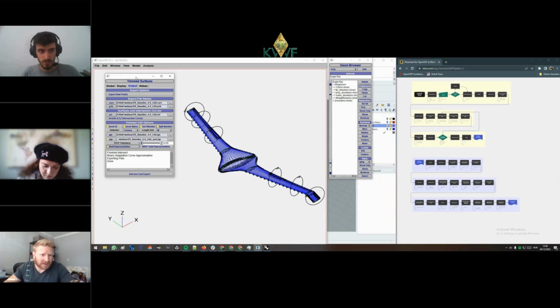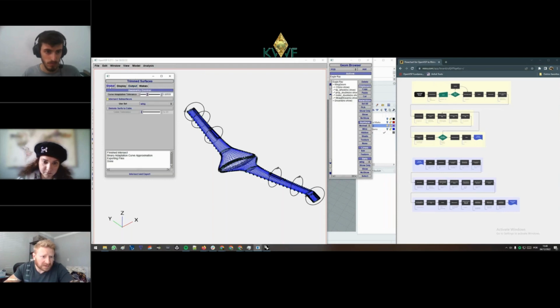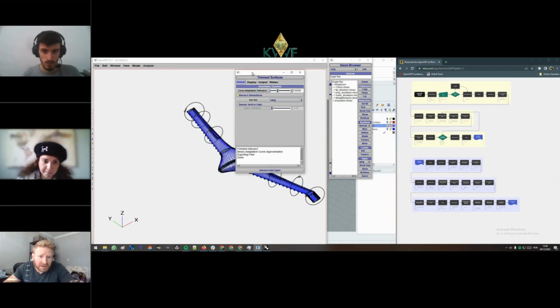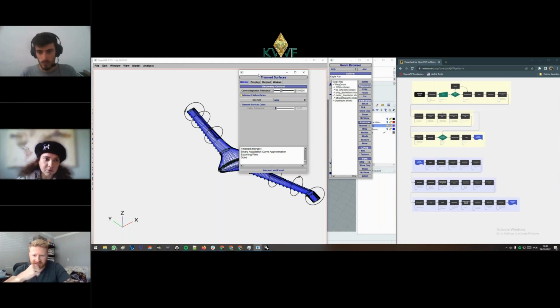Let's see. And in your global settings here in OpenVSP, can you click on the global tab there? Yeah. So I noticed that when you come into Rhino, you're already trying to do that. Essentially, it's rebuilding the surfaces and trying to do effectively a cubic fit instead of using the full Bezier definition.